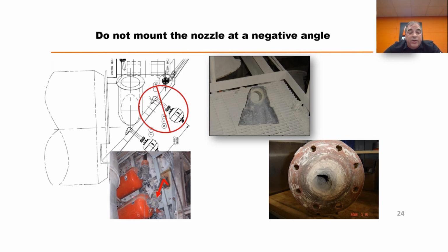As you can see on the little illustration, there's a 90-degree nozzle shooting down a kiln inlet. When that nozzle wears off, there's a hole in it. So if the cannon blasts a few times, it'll blast out into the middle of nowhere, and then material will pour down into that nozzle and fill it up, like this bottom right-hand photo. When that happens, that cannon is useless.